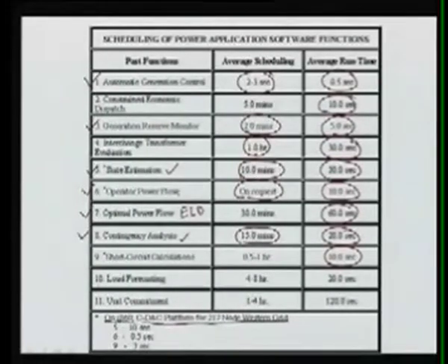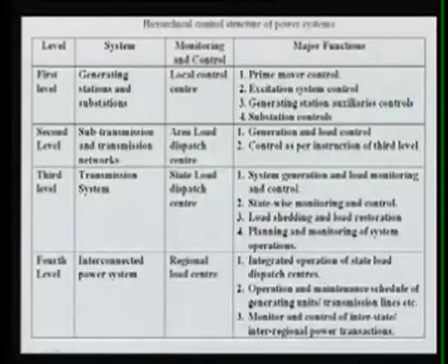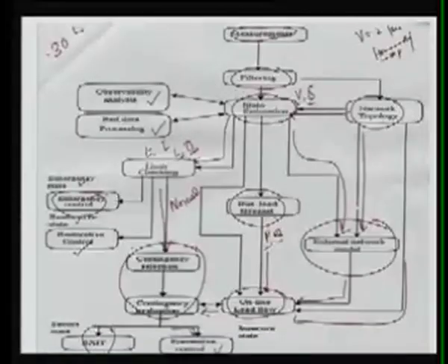Load forecasting. Again, the load forecasting can be done in different fashions. Load forecasting can be of different types, whether it is long term, medium term, or short term load forecasting. Again, this short term load forecasting can be categorized at various intervals. It may be for 1 day, it may be hourly, it may even be half hourly. We saw in the previous section that we require the load forecasting within 30 minutes.